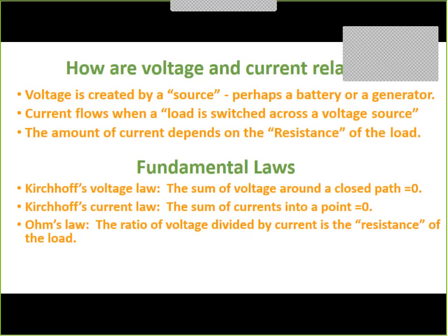The amount of current that flows in the grid depends on the resistance of the load. The resistance is a quantity that describes the behavior of the device. There are 3 fundamental laws that we have to obey, and these fundamental laws are used in cybersecurity in various ways. If we want to see if somebody's messing with our numbers in a SCADA system or in a state estimator, we check to see whether the data satisfies Kirchhoff's laws or Ohm's law. And we can check that because we have a model.